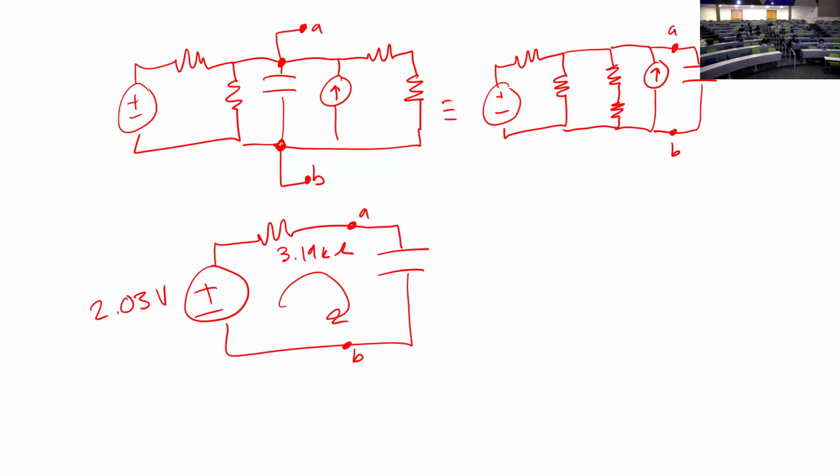Yes, one capacitor, or technically one inductor, but you should expect one capacitor. Technically, it depends. You would call that second order, but you can model it as first order if they are perfectly in parallel or series. But if they're separated beyond that, it becomes a true second order.